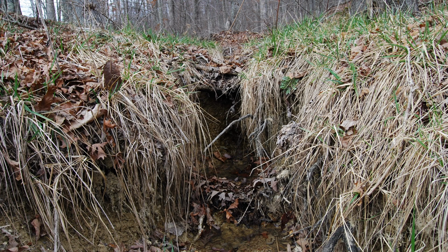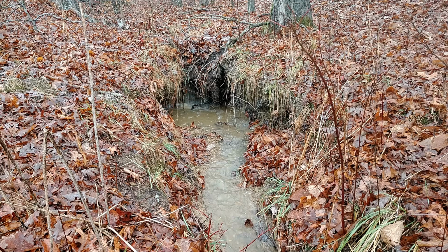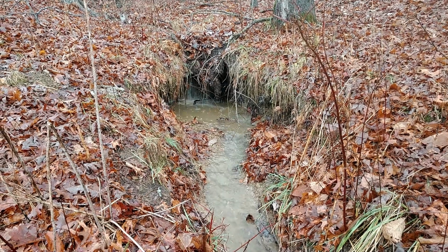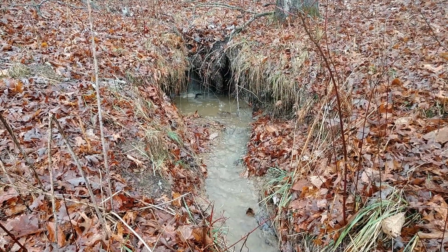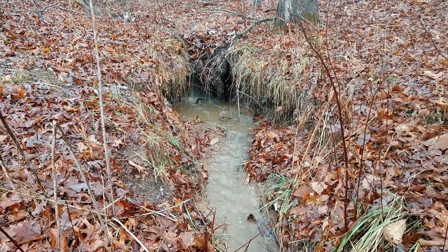The vertical drop-off created by the dozer quickly became a head cut that moved up the valley during runoff events. The stream only carries water 2 or 3 times a year, but each time the stream flows, the head cut becomes deeper and wider and moves a little bit more uphill.